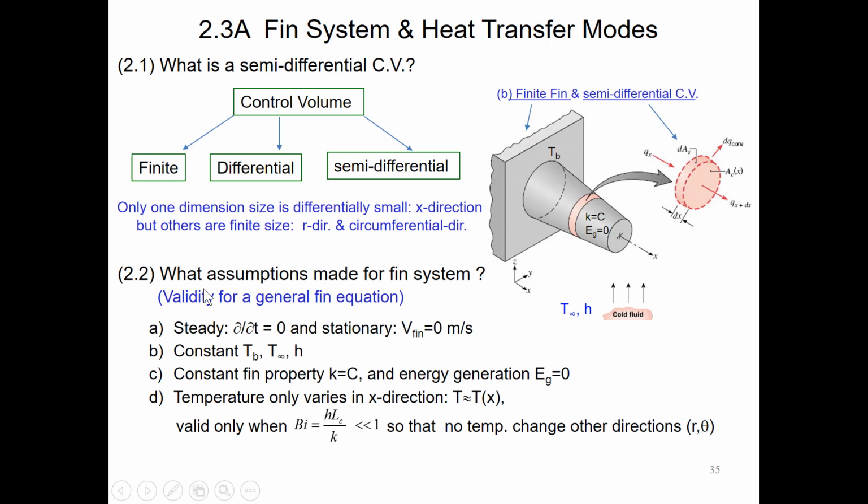The second question raised is, what assumptions are made for our fin system? A. It is at a steady state and it is a stationary fin. B. The fin system has a constant fin base temperature, fluid temperature, and a constant heat transfer coefficient. C. The fin has constant property of conductivity and zero internal energy generation.